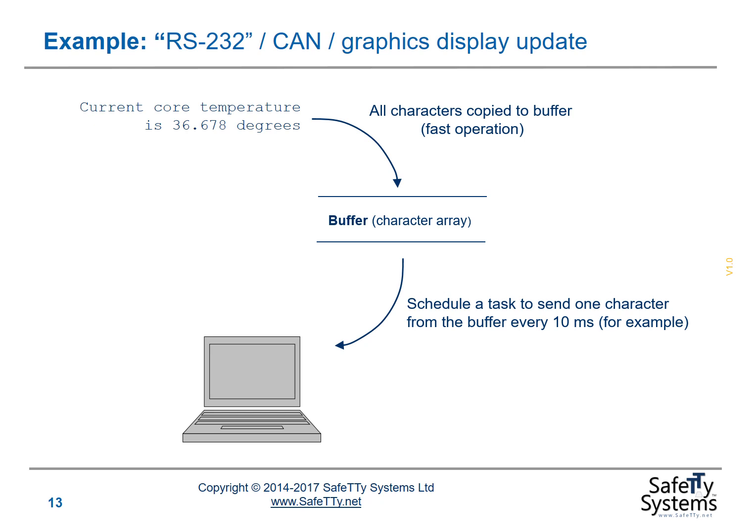Now if you think about the previous version of this system, it took me about 42 milliseconds of CPU time to send these data directly from here to here, because I was essentially sitting and waiting for each character to be sent. So I was passing the data to the UART, and I'm sitting there saying, have you sent it yet? Have you sent it yet? But that's a pretty stupid architecture, fundamentally.